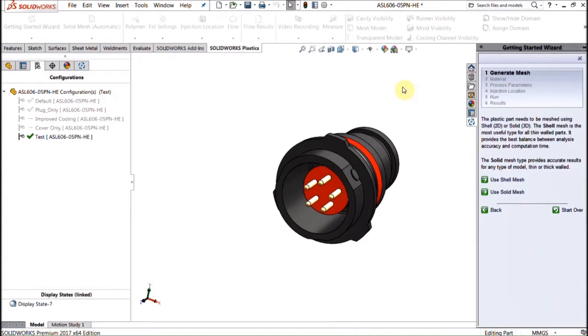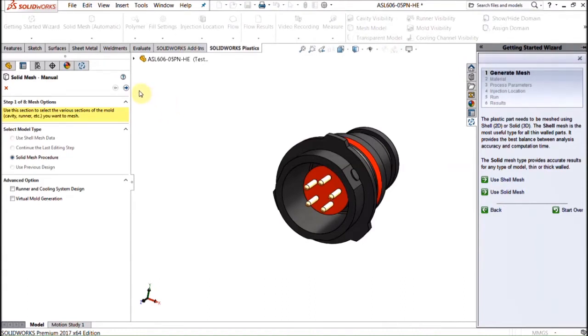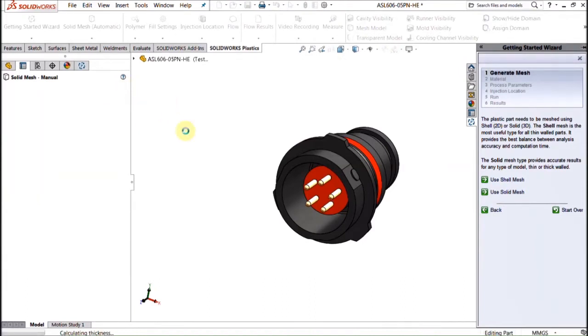split that up into some discrete elements, individual pieces, that have some known equations in them, and then the simulation will figure out what the velocity and temperature and pressure of the molten plastic is in all these elements as the manufacturing process is happening, of course. And so there's always a trade-off between the detail in the mesh, the size of the element, and how long it's going to take for the calculation to run. And that's one of the key choices to make here.